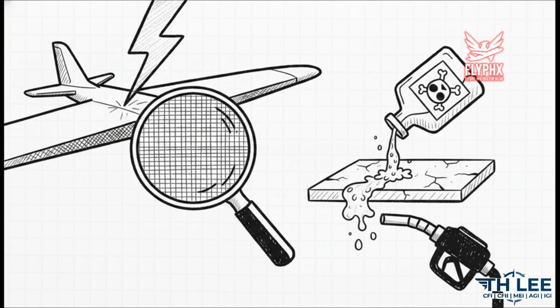You see, fiberglass is an electrical insulator, while carbon fiber conducts electricity very poorly. Therefore, lightning protection requires fine metal meshes, usually made of aluminum or copper, bonded directly into the outside layer of the composite skin. This safely conducts that massive electrical energy overboard and away from your delicate avionics. By the way, because fiberglass is transparent to radio frequencies, you'll very often find internal radio antennas placed strategically behind special windows cut into that lightning mesh.